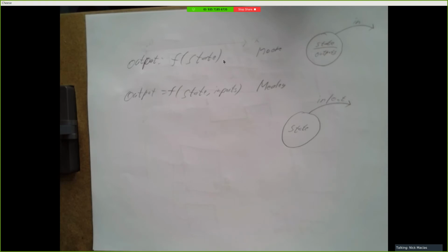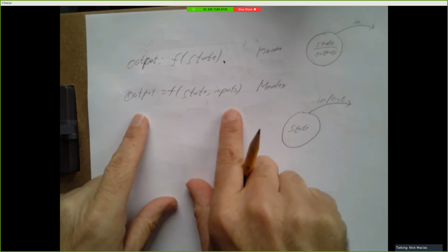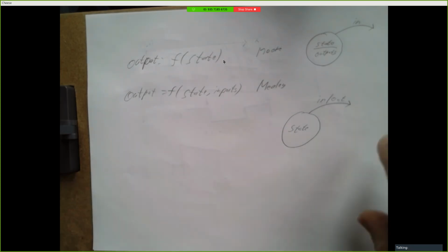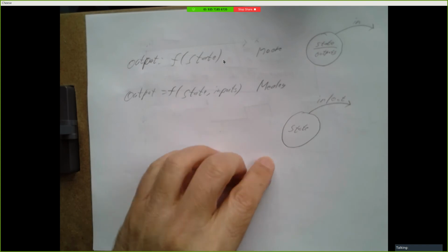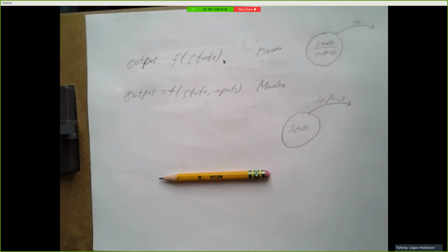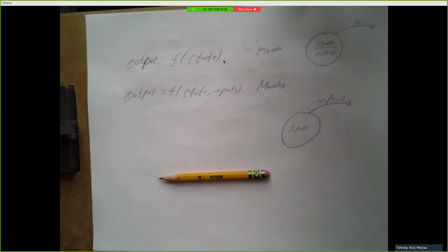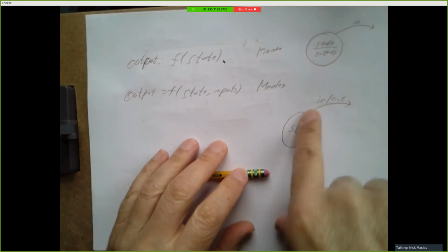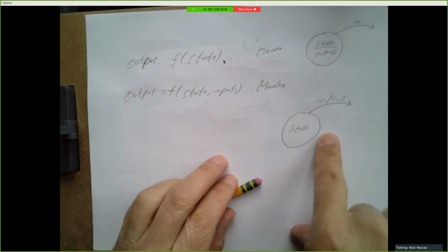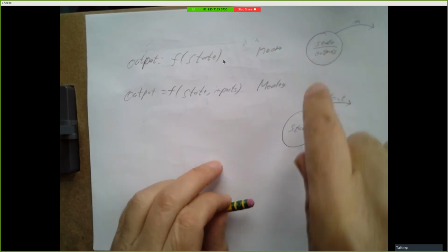When you look at your Z equation, if it depends just on the states of the flip-flops, then it's going to be a Moore machine. And in practice, some outputs might be Mealy outputs and some might be Moore, but first order, if any outputs depend on the inputs, call it a Mealy machine and use this to show your state transitions and your outputs. So either way you show the outputs, it just depends where you put the outputs. Exactly, yeah. And you could always show it like this, but it's simpler if the input doesn't affect the output, just list the output right there in that bubble.